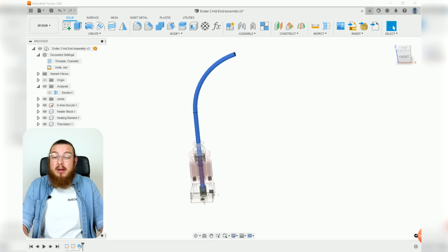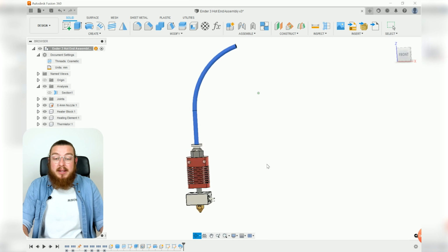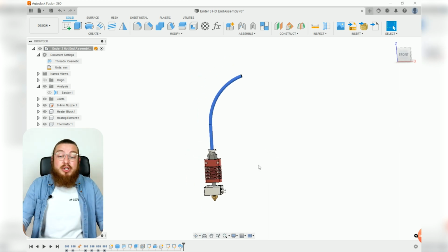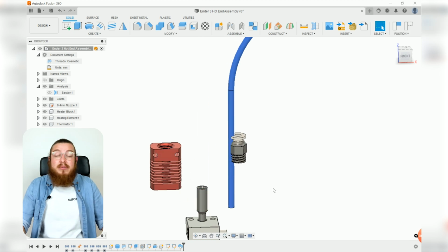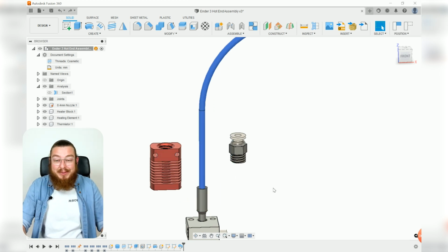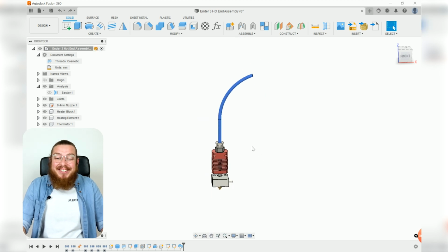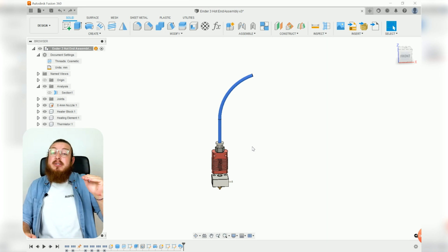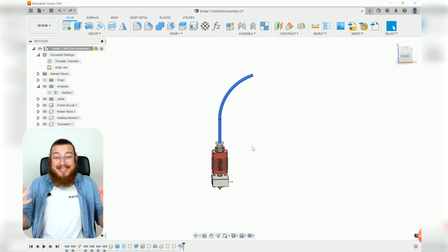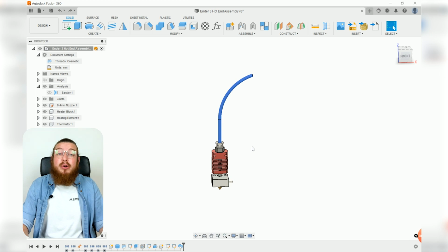So I'm going to be turning back on all the components and then reactivating that top piece. That looks great. But as I'm sure you're all worried about, all these components can move. Big, big issue. Let me just undo all of that. So if we wanted to, because all of our pieces are in the right location, we could go individually and add an as-built joint to every single component, back and forth, back and forth. That's going to take a while. Engineers are lazy, so let's add in what's called a rigid group.